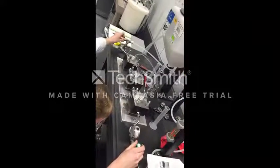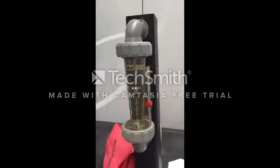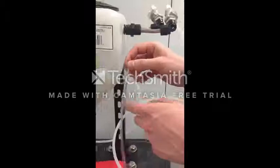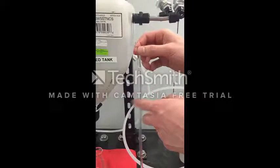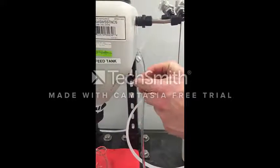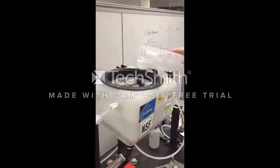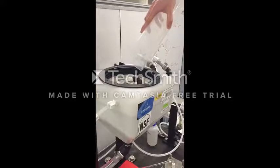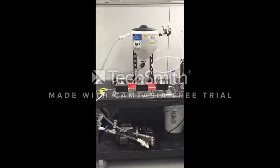Adjust the flow rate and pressure regulator to desired operating conditions. Allow the system to equilibrate for at least 20 minutes. Purge the collection tubes of any air bubbles. Add a saltwater solution to the feed tank, bringing the feed to a known concentration. Allow the system to equilibrate once again.